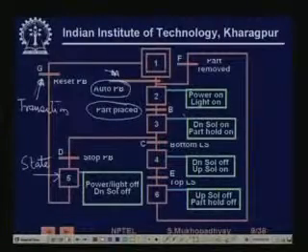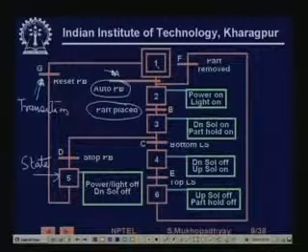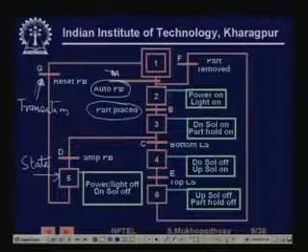On the other hand, these green rectangles indicate the outputs which are on at each state. For example, you can see that in state 1 nothing is on, none of the outputs are exercised, while in state 2 the power and lights are on. In state 3 the down solenoid is on. Actually, this is the state when the solenoid is coming down.